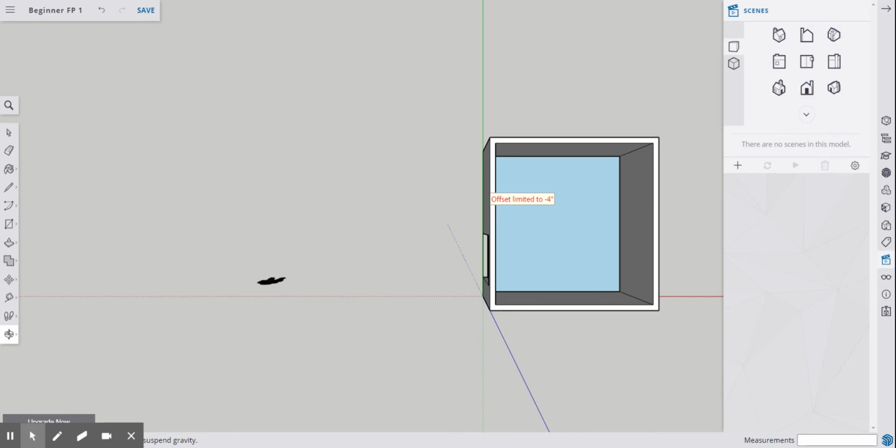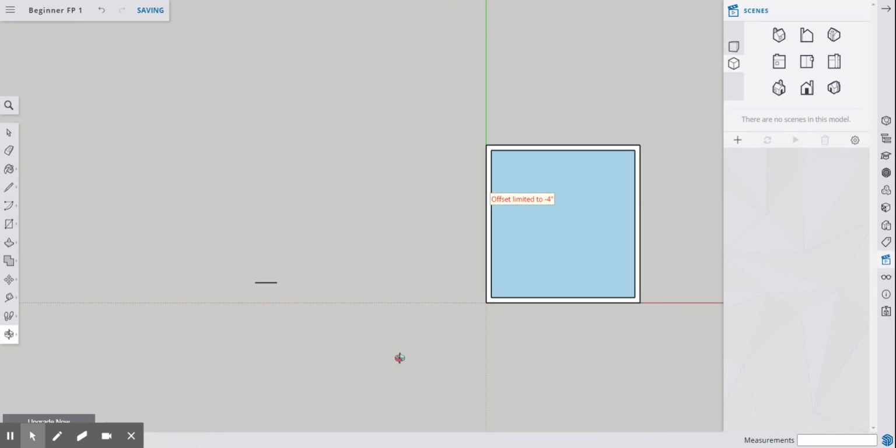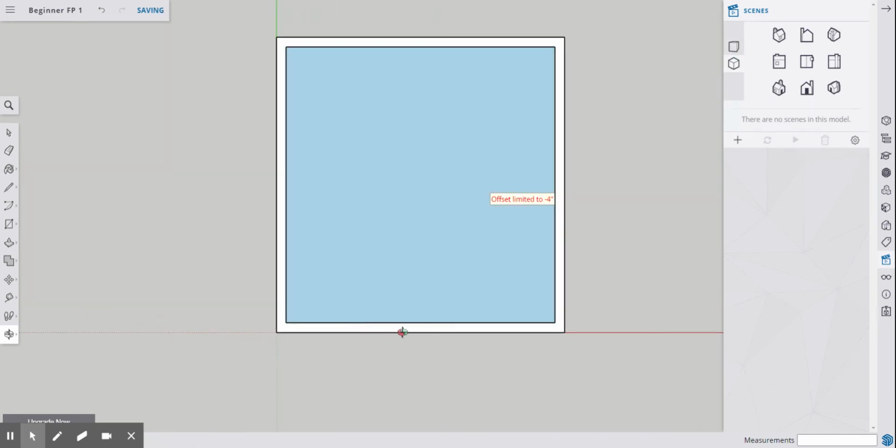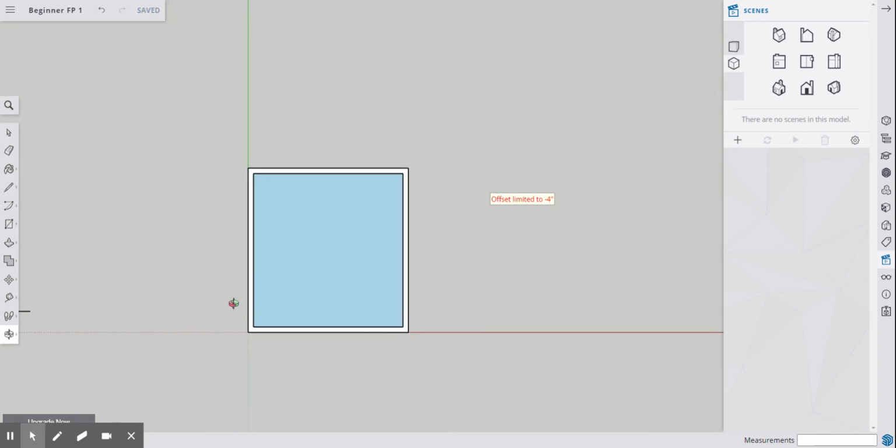So let's say we're going to get the floor plan of this 10 by 10 room. We would obviously click the top view, and something that you have to do is there's two different views it gives you. We are in perspective, but when you need to get any of the plans, sections, or elevations, you need to be in parallel projection. This is this little cube right here, and you click it.